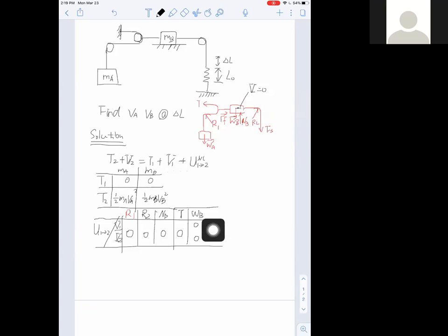As you may notice, starting from this weight force, I write the potential energy instead of the work done by the weight force. That's because the weight force is a conservative force, so it can be written as the potential energy V1, V2. Okay, next we have the weight force WA.